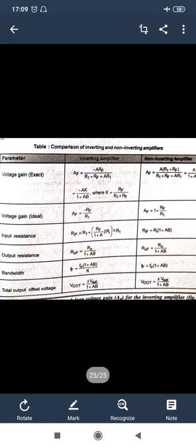Input resistance, when we use the non-inverting amplifier, we use the voltage series, and whenever we use the series topology, in this case input impedance always increases with the D factor, means RF is equal to Ri into D, and D is equal to 1 plus A beta, that is the desensitivity. So RF is equal to Ri (1 plus A beta). And in case of the inverting amplifier, that is used in the voltage shunt topology, in series we increase the input resistance, but in case of shunt topology we decrease the resistance, so it is nearly equal to the value of R1.